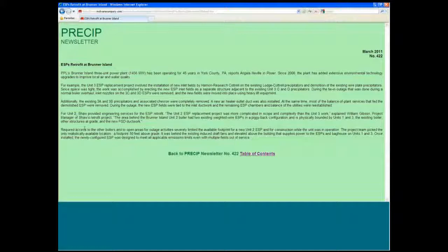You can add fields. You can combine the existing dry precipitator with a wet precipitator. That's one of the things that we recommend not be excluded from coverage. If you have to get very ultra-high emission levels, rather than just replace your precipitator with a fabric filter, you can use the existing precipitator to capture the fly ash and still make it saleable.